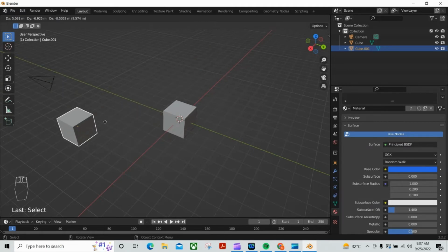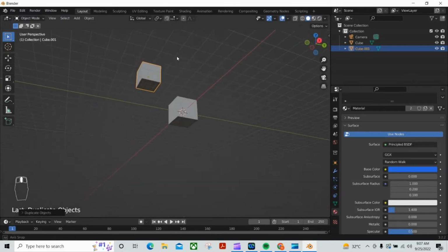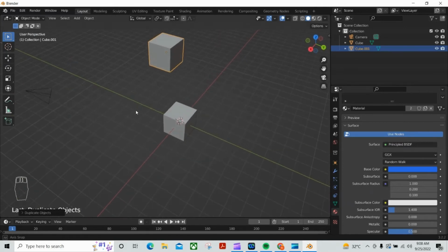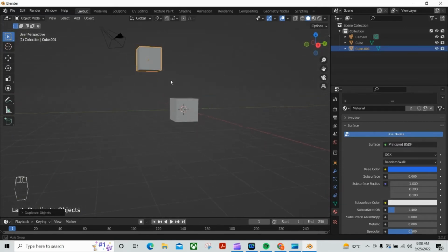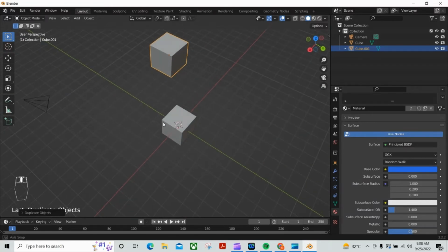And if you see, you can move it here and there, but most of the time you have to do it with the Z axis or X axis or Y axis. Otherwise you put your object anywhere and you will not be able to define it. Suppose I put it here, you see how it went. So this is what we don't want generally. If you want, in that case you just go with the Z axis and X axis.